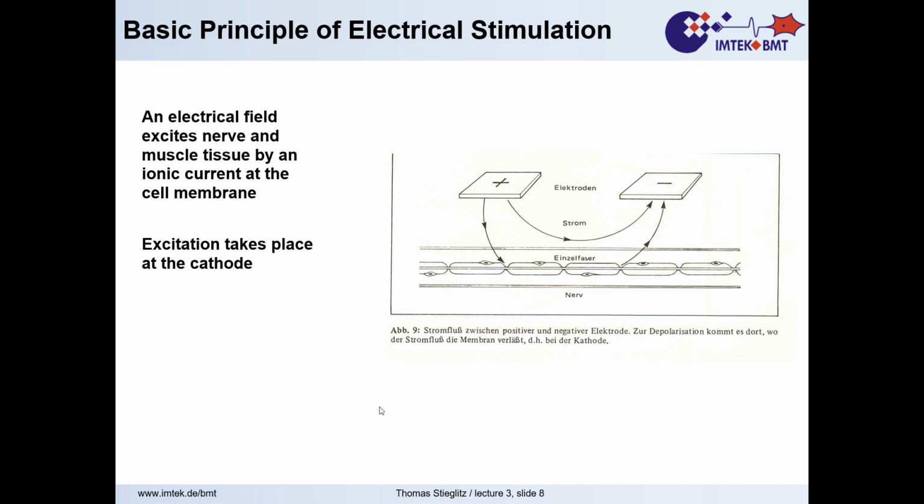What we should keep in mind, and this is not fully correctly drawn on that figure here, is that field lines are always orthogonal to metallic surfaces. So if we have metal electrodes, we have to imagine that the field lines leave orthogonally, then go somehow through the volume, and they end up orthogonally.